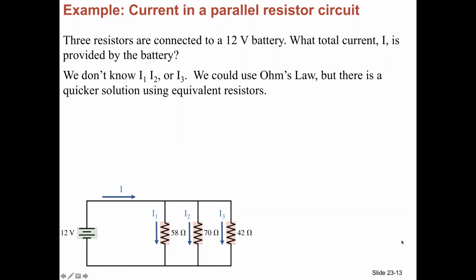All right, so it looks like as you guys work, I'm seeing kind of 2 different answers here. 218 amps and about 2/3 of an amp. So we'll see what it is in a second, but 218 seems quite big. Remember, 1 to 10 amps is a household current range. So that seems fairly high for a 12-volt battery. So go and check your algebra again.